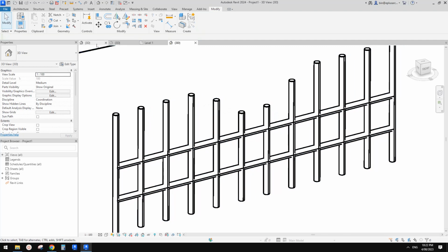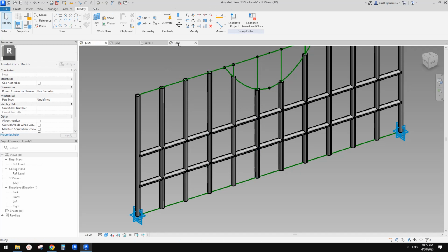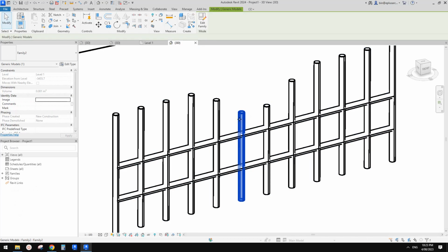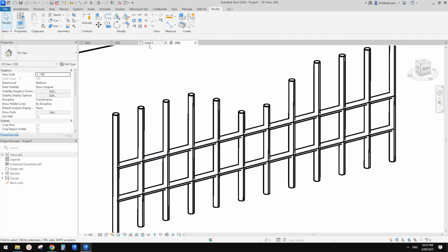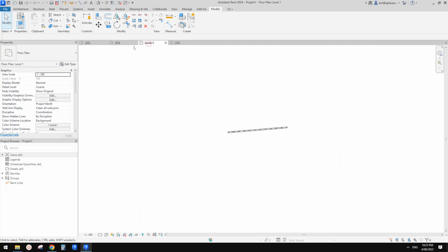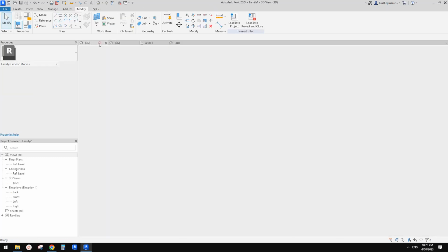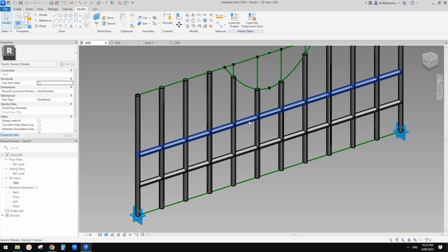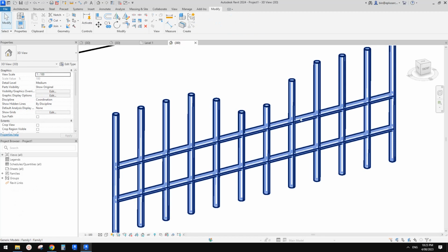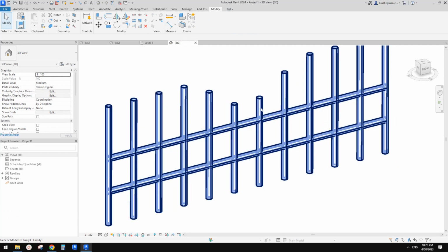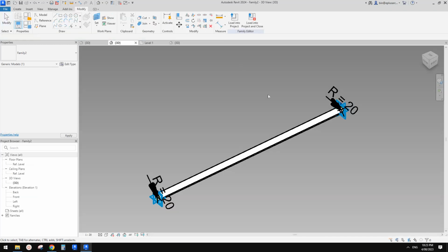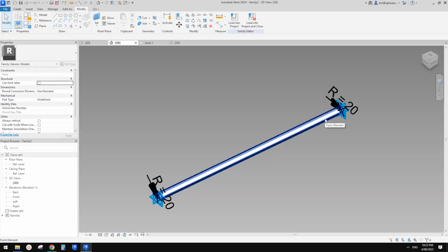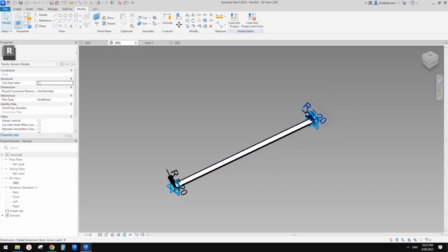Because previously we directly edited this family, so this one, and loaded it and overwrote here, and then after that I edited this one, and loaded it back into the project and overwrote. So which means I overwrote it back. So this family is now without that radius parameter. So the radius parameters are here because I didn't close this family.